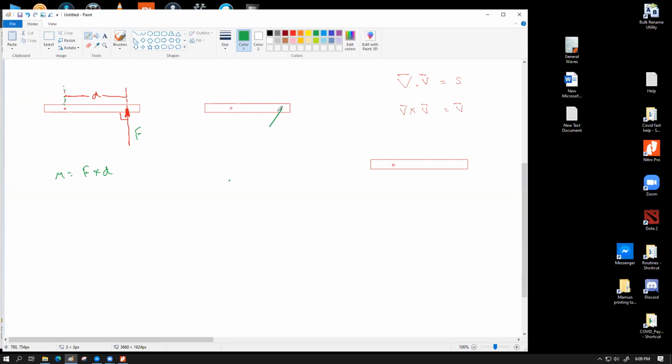So if the force is applied at some angle with the object's axis, then how we're going to deal with this? In the same way, let's say the defined distance between the applied force and the pivot point is given as d. So here the angle is no longer 90 degrees. So how can we work with that? One easy way, the typical way to find out how much moment we produce is that we have to find out what is the perpendicular distance of this force from the pivot point. So we have to somehow draw a normal line from the pivot point onto the force.